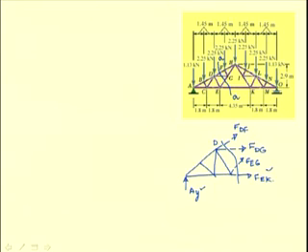We see that these two forces, the force in the member DG and the force in the member EG, are concurrent at G. So, it is convenient to take moment about G to determine the force in DF. Same way, the force in DF and the force in DG are concurrent at D. So, a moment about this point can be used to determine the force in EG. So, let us start by considering first the moment about D to be 0.